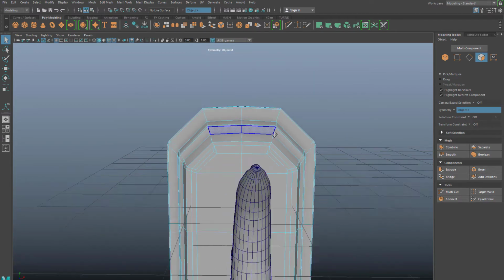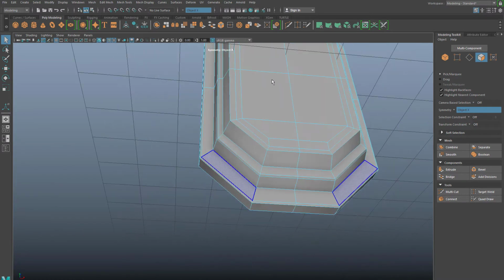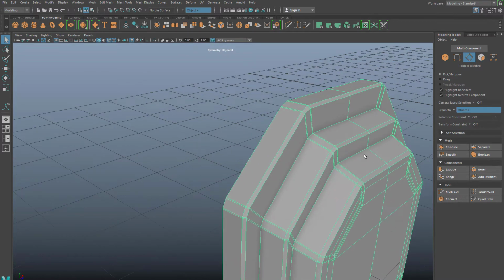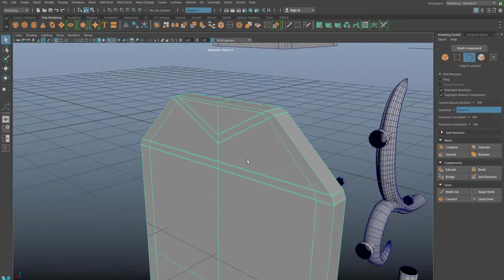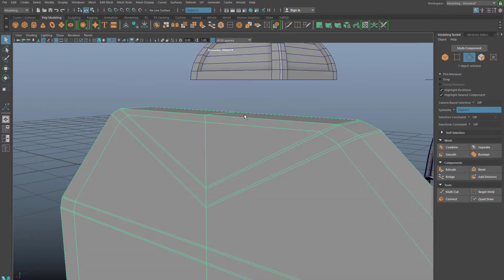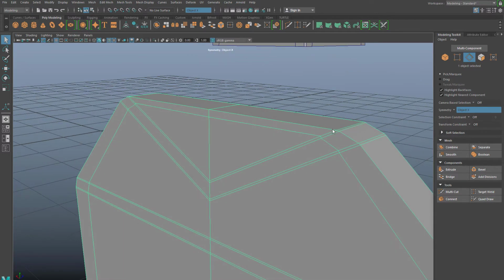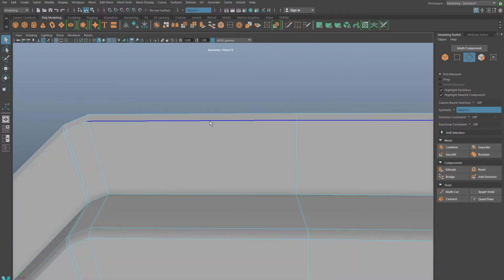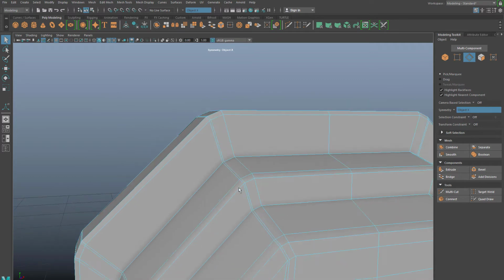Now what happened with you? Why does that have a round angle to it? So I went and this is cut, but I just had to undo some stuff. So apparently when I took care of this, it shifted everything down so that it had a round top. So what I have to do is be mindful not to eliminate this edge loop here. Now that one's fine, but leave that because this is an extra wide bevel, but I want to make sure to leave that flat top.